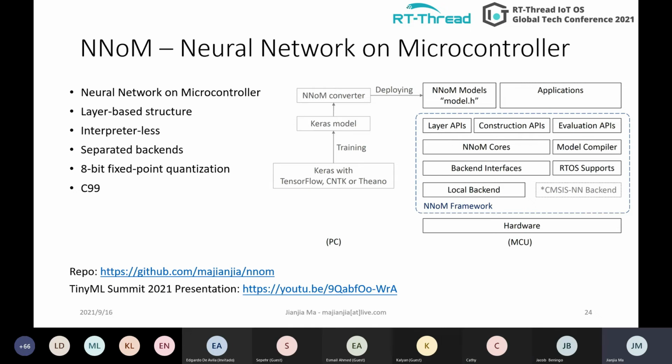During the development, I also used the msh shell to transmit data files to the microcontroller. It supports YModem, so I used YModem to transfer the data to the MCU for data validation. I also used the console to interact with the library, so I can control it. I also used the memory debugging method provided by the RTThread, so that I can find memory leaks very easily.